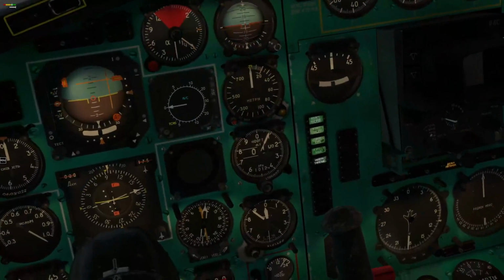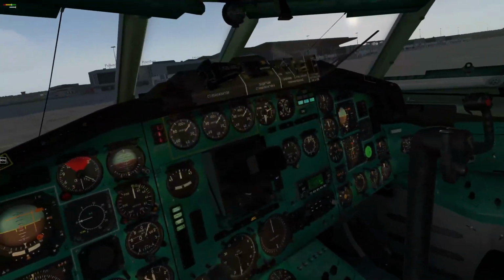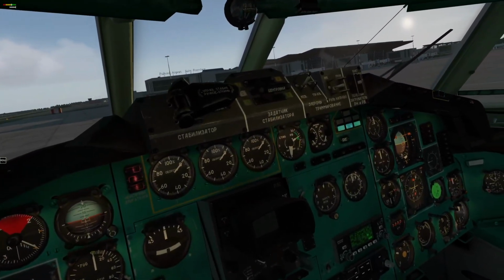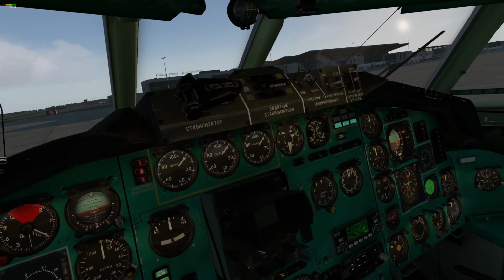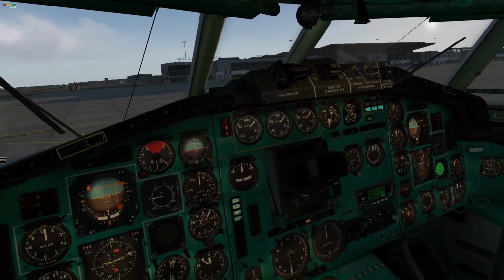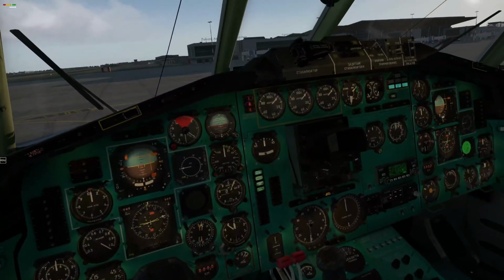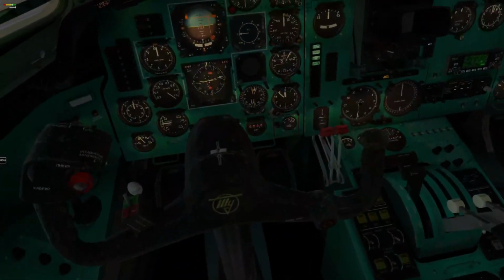So, first of all, our trims are in neutral. We open the emergency trim cover and check it. Full up. And we wait for it to come to the full up position. We can control it for this gauge. You can see it moving. Okay.